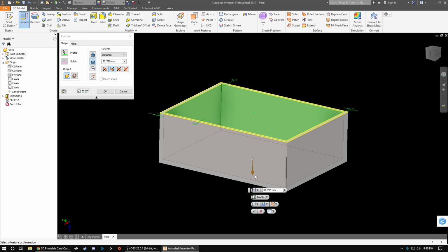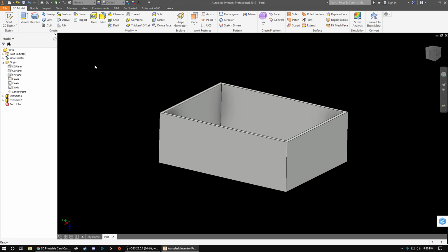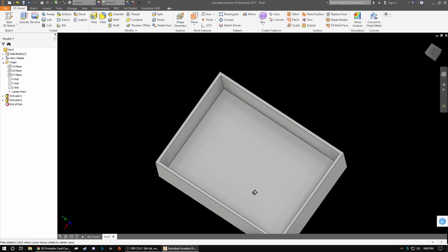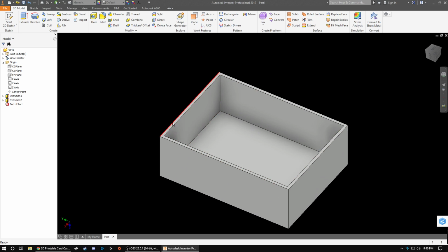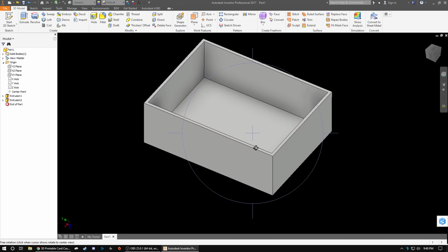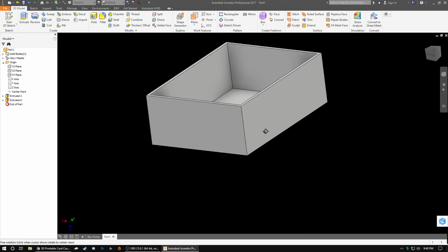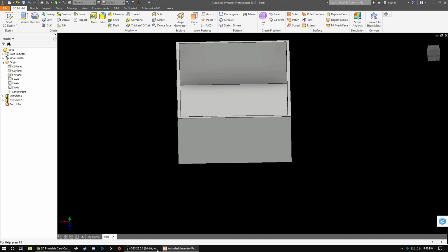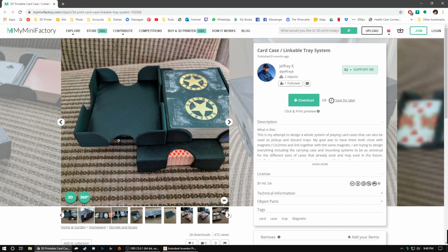We made this 35 millimeters deep, so I want to keep a consistent distance around everything. So I can type in 32, or I can go 35 minus 3. And now I know that that bottom is going to be the same as these widths here, because I made those 3. Okay, so that's starting to look a little bit closer to this guy here.